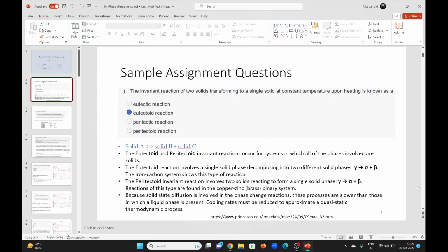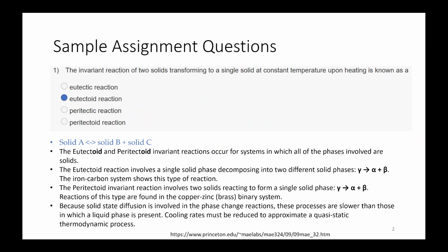Because in case of crystalline structures, you know the equilibrium distance and all that you have studied, right? The equilibrium distance will be followed in a particular unit cell. Your atoms are sitting there at an equilibrium distance. So this all will make your system more energy favorable. If you are solidifying your material very slowly, then it is more likely to solidify into a crystalline structure, which is more stable.